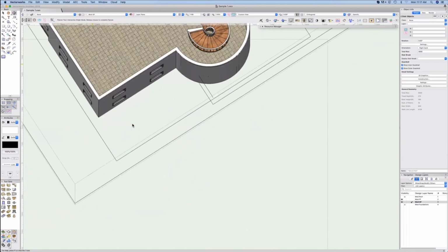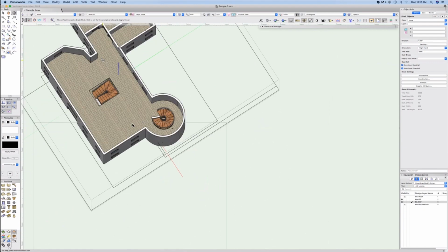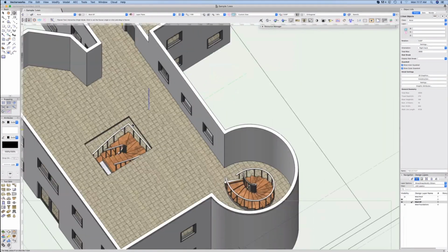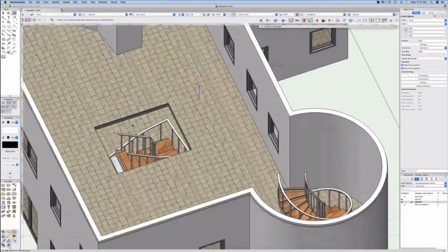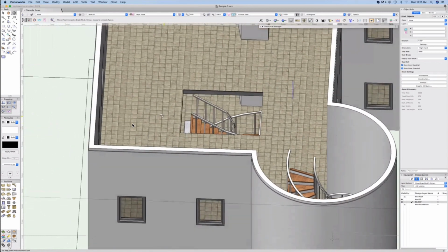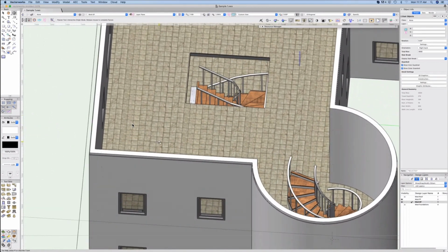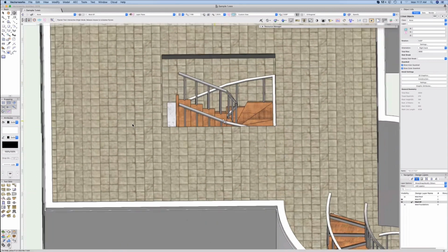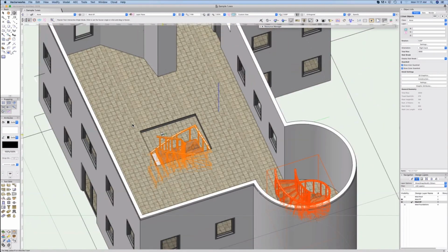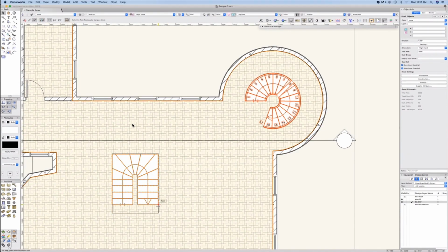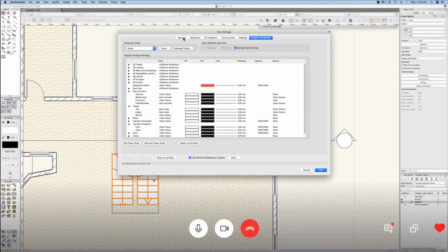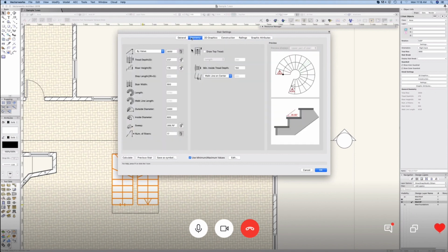Yeah, looking good. There is one other setting in the stair tool called Draw Top Step, but normally the top step is actually the slab itself. So all you need to do with that stair is move it tight to the slab in top plan, and then the slab itself is your last step, if you like. If you wanted though, you could draw that top step in if you prefer. So double click on the stair, let's do it. Is it under general or geometry? I'm not sure, one of those. Yeah, there we go. Draw top step in the middle section there.